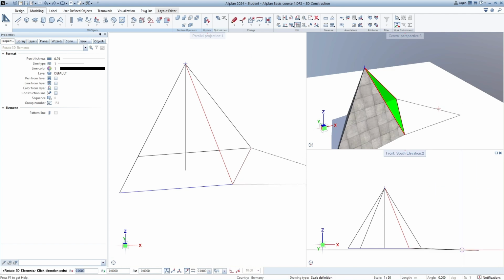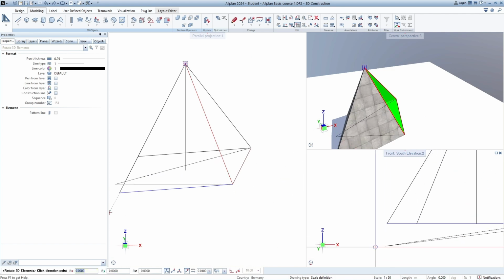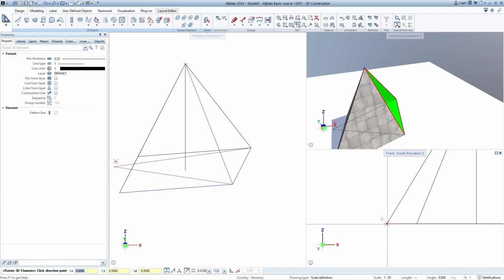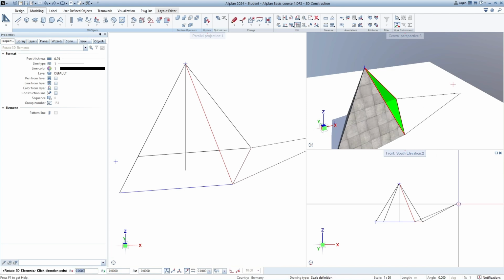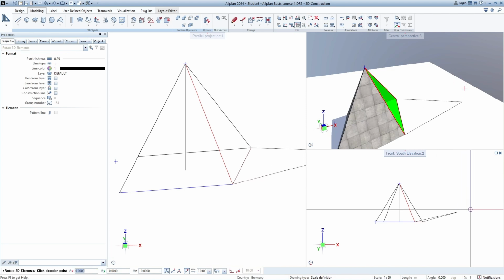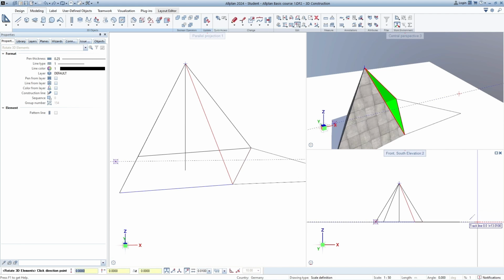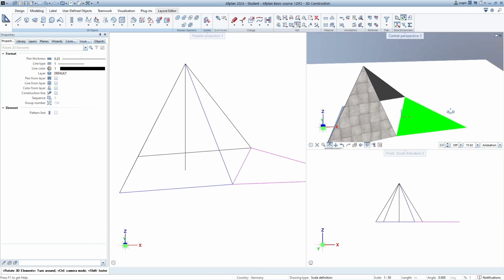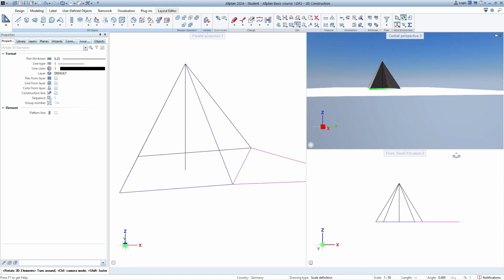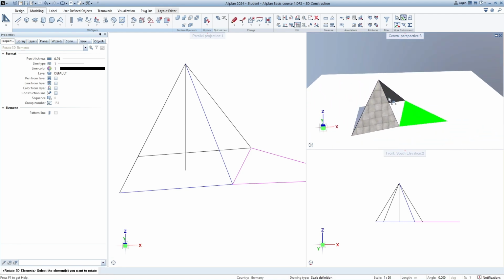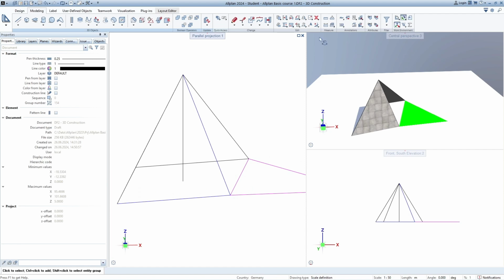So what we're going to do is we hover over, for example, that point. And as soon as you keep your cursor longer than 1 second there, you have a track line that is being connected. And as soon as we go into the plan with this kind of surface, just like that, we will catch the track line. And as soon as we do a left click, we can see that this kind of surface is now put outwards and exactly in the plan view. And we can basically do that for all the kind of surfaces.